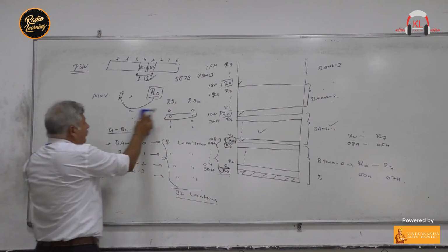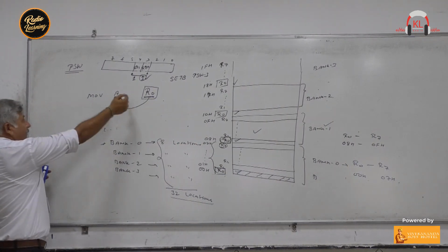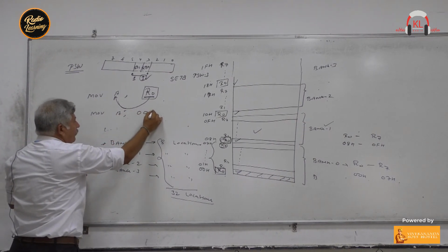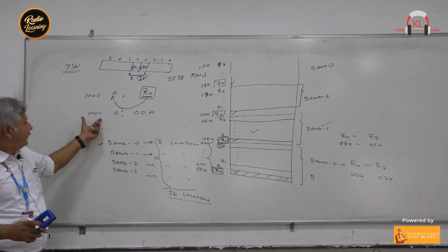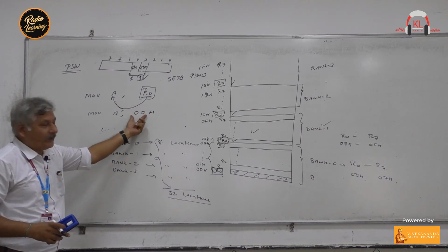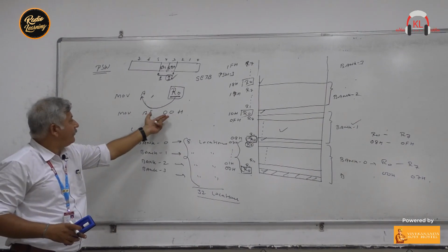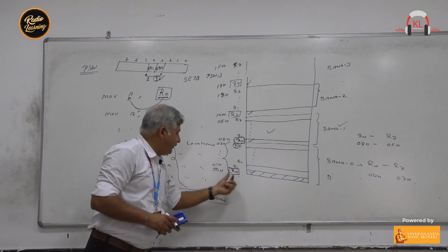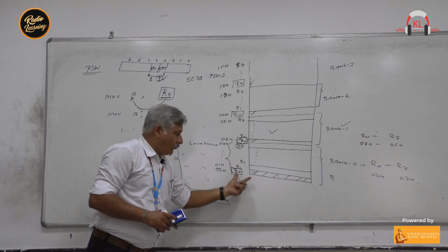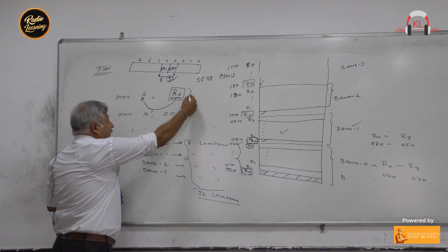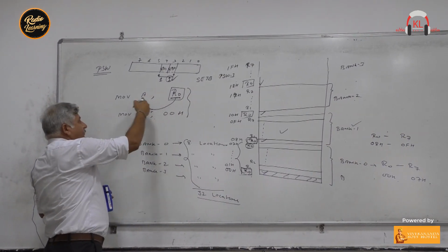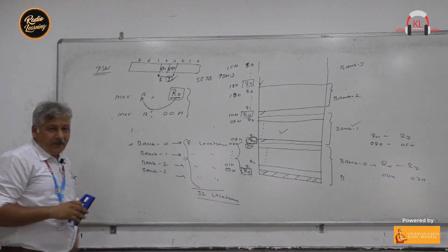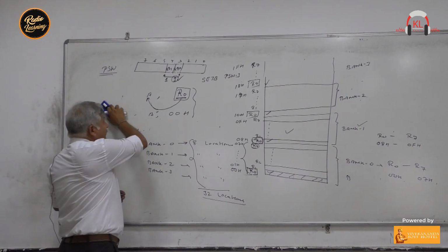Right? Same way, for example, in this instruction, in place of this, I can write this also. MOV A, 00H. Now what will happen? Data from address 00H will be moved in A. What is the 00H address? 00H address is the address of R0 register. So in this case and in this second case, both the instructions are performing same operation. Right? So this is about the register banks.